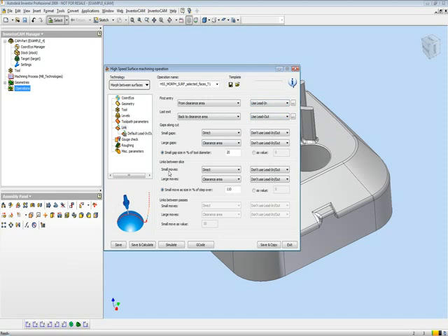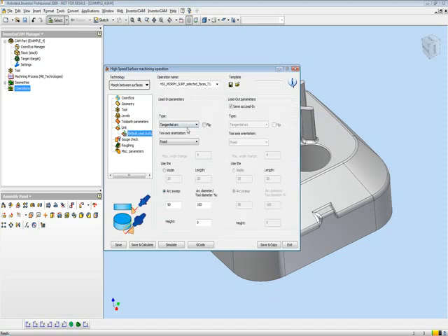And in my link between slices, I'll just simply change my large moves to direct. Now, in my default lead in, I'll have my lead in itself as a vertical tangent, but my lead out, I'll change that to a regular tangential arc.